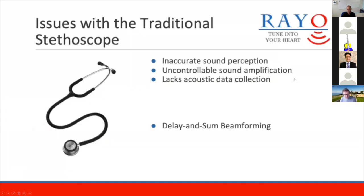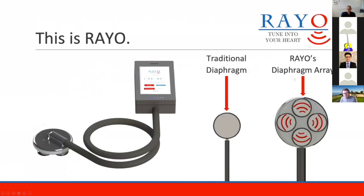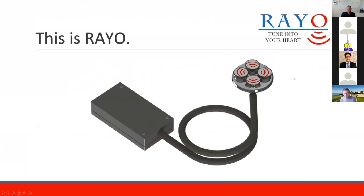Delay and sum beamforming is a signals processing technique that allows us to isolate a particular sound source within a noisy environment. And because everything is electronic, we can easily implement some form of volume control and data collection. The end result is Rio, the world's first beamforming electronic stethoscope, designed to minimize the risk of misdiagnosis and detect heart defects without EKG or imaging. Using this powerful device, doctors can diagnose and provide treatment without having to run uncomfortable tests.